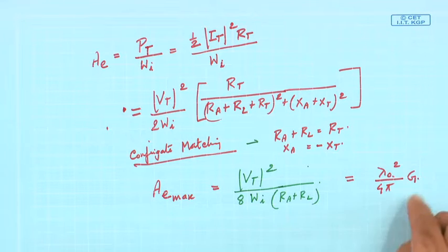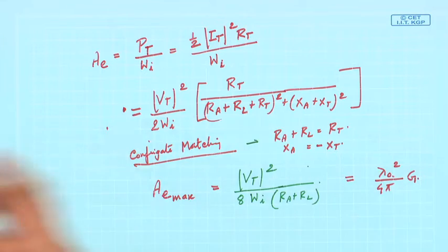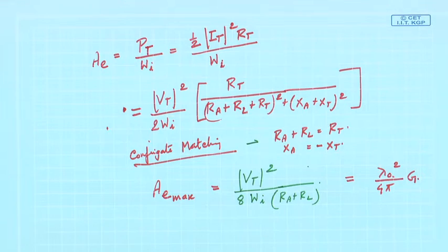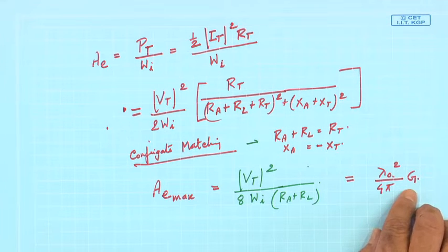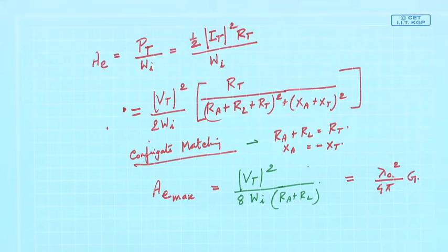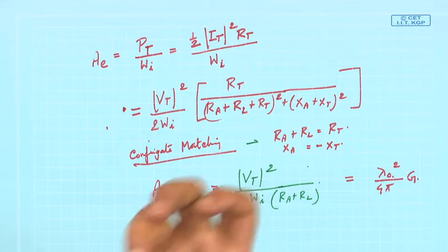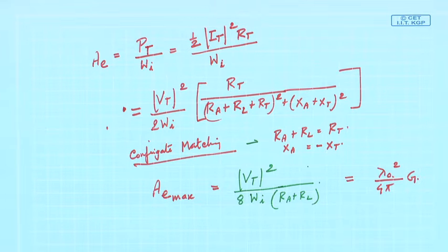Transmitting characteristic is G, we know how to measure G: you find the power pattern, you find the power distribution at various points, and from that you can find out the maximum G. So, if the same antenna we use as a receiving antenna, you can find what will be its effective area. The same antenna which you have characterized with its spatial gain, now you know how much power it will be able to receive.